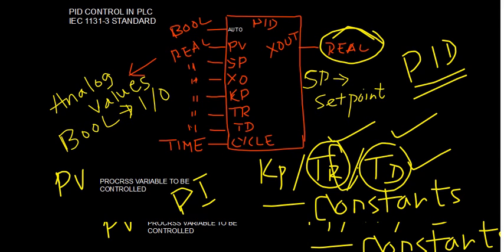As far as implementation is concerned, that will slightly change from PLC to PLC, but the ladder diagrams, the logic or sequence of operation, the use of the bits, the input switches and output switches, all those things will remain the same. They will not change as the PLC manufacturers manufacture different types of PLCs.